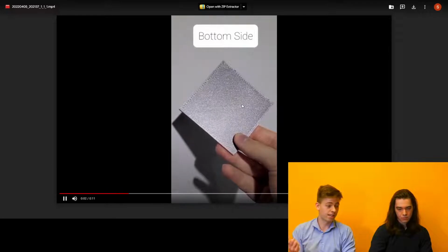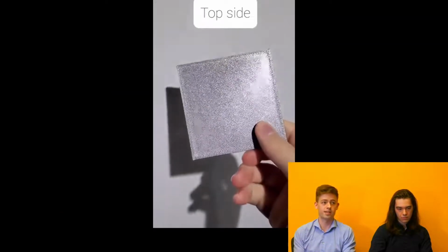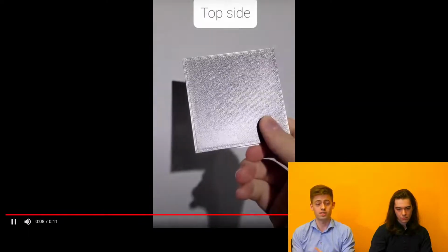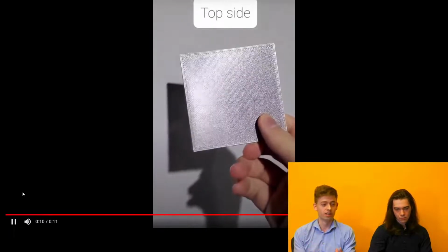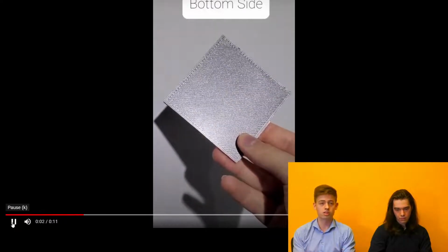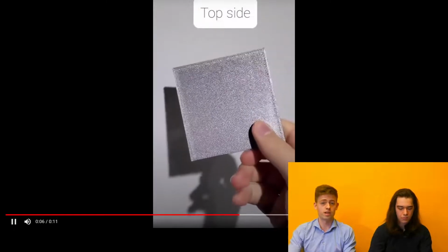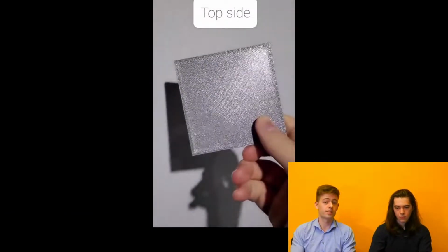That's one thing that when I started printing way back, I printed on glass, and it was really cool to see a super glossy bottom. But in reality, if you're trying to make a thing that looks good, you actually want all sides to look about the same instead of just one really glossy side. Or in the case of textured surfaces, sometimes it's okay to have one side that's really rough and textured, but other times you just want all the sides to be the same sheet.